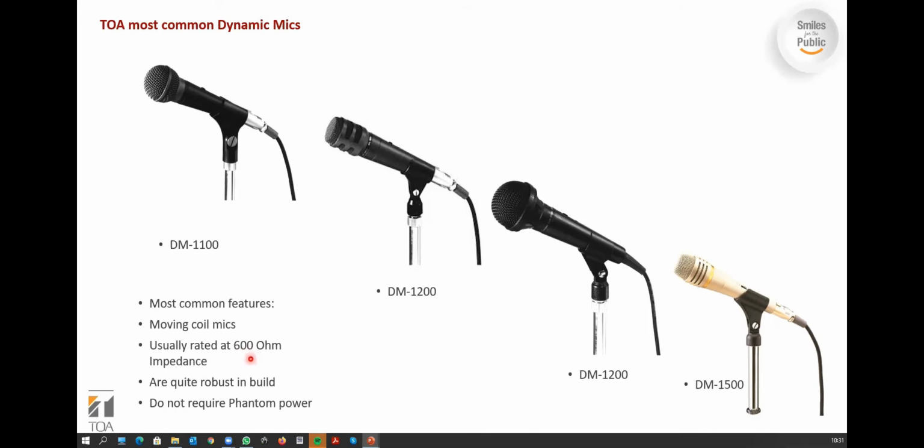As you know, guys, the technical team on this forum, with our normal line array speakers, our big bass bins, our big speakers that we normally have at a function, these are normally 4 ohm speakers rated at 500 watt, or can be 8 ohm speakers rated at 250 watt for argument's sake. These are normally low impedance values. Speakers are normally in the range of 2, 4, 8, 16 ohm. The max you can find is about 32 ohm, but these are normally in telephone handsets. But standard dynamic microphones are normally rated at 600 ohm.